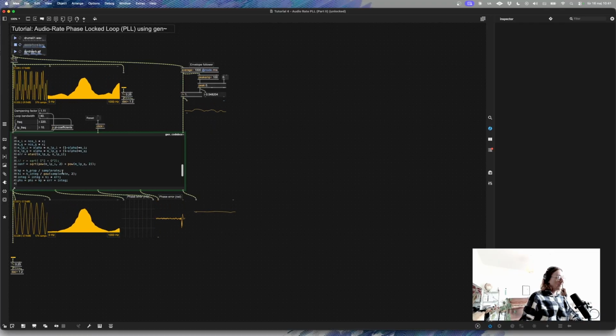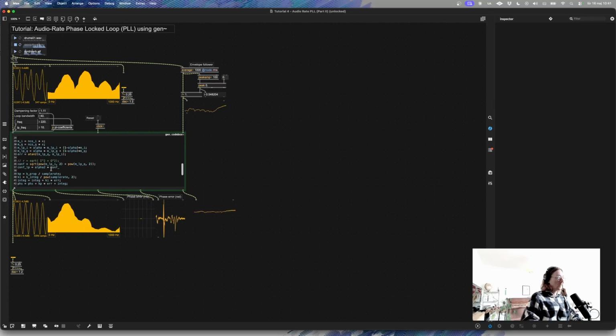And then we update the confidence low pass in the same way that we did for the I and Q component. So we have our alpha 2 coefficient, the previous low pass output, and then 1 minus the filter coefficient times the input, which is the raw confidence value.